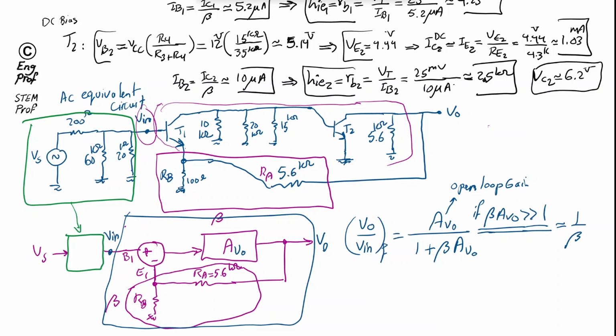So a quick rule of thumb, or a quick first order analysis of the feedback voltage gain in the system, assuming this is true, which is questionable and might not be exactly true. Beta in this system, as we talked about, is 1 over 57. One more time, beta is RB over RA plus RB, a voltage division between these two.